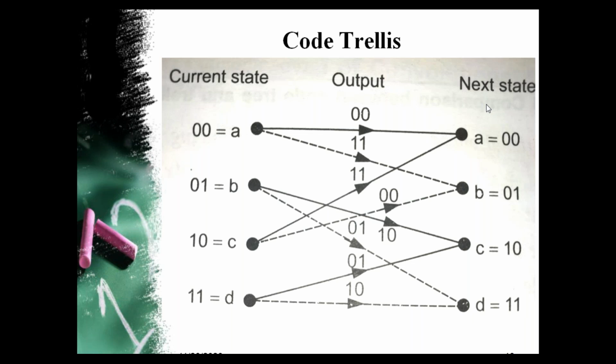If the constraint length is 4, we can have 8 states for the encoder. Then we will have to represent those 8 states twice. One as current state, that is A, B, C, D, E, F, G, H, like that, and then again the next state, all the 8 states. Here in this convolutional encoder there are only 4 states, therefore we have represented ABCD as the current state and ABCD as the next state. That is, we have represented all the possible states twice.